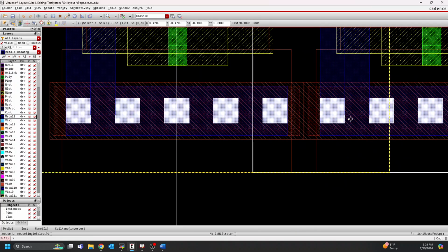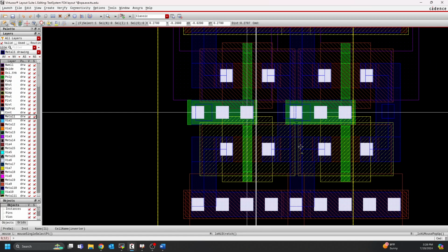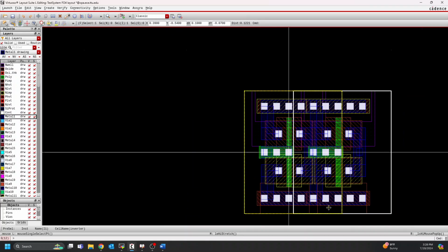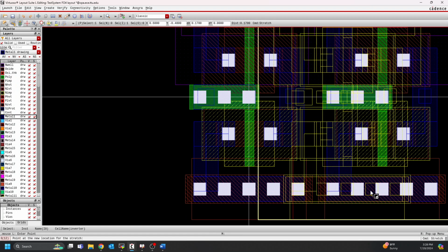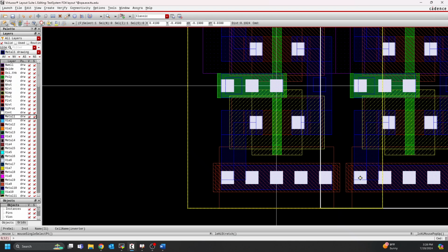We can see that if we put them right on top of each other to try and pass one way, then we get some things shorted together here. So that's not good. Our output of our first stage is shorted to ground in this case. Whereas if we move this over to where it has enough space, now these things aren't connected. So this makes more work for us. We have to manually make these connections here.